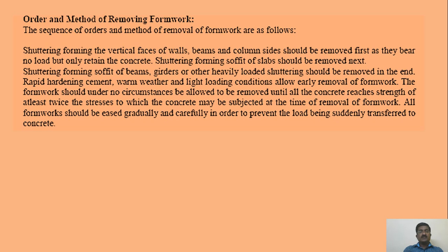Rapid hardening cement, warm weather or light loading conditions allow early removal of formwork. The formwork should under no circumstances be allowed to be removed until the concrete reaches a strength of at least twice the stresses to which the concrete may be subjected at the time of removal of formwork. All formwork should be eased gradually and carefully in order to prevent the load being suddenly transferred to the concrete.